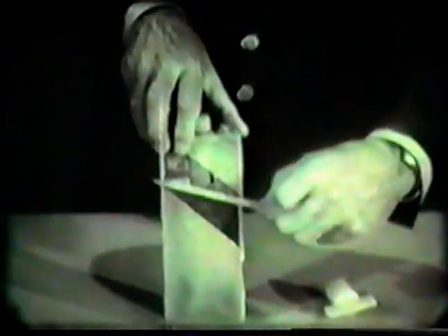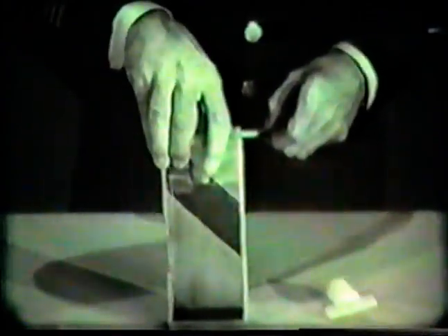The cells in nickel-cadmium batteries are thinner and lighter in weight than lead-acid battery cells. The negative plate group and positive plate group are sandwiched together as in a lead-acid battery. The plate separators consist of nylon fabric and cellophane. The cell case is of molded nylon, and since shedding from the plates is no problem, space is not required at the bottom to collect debris.